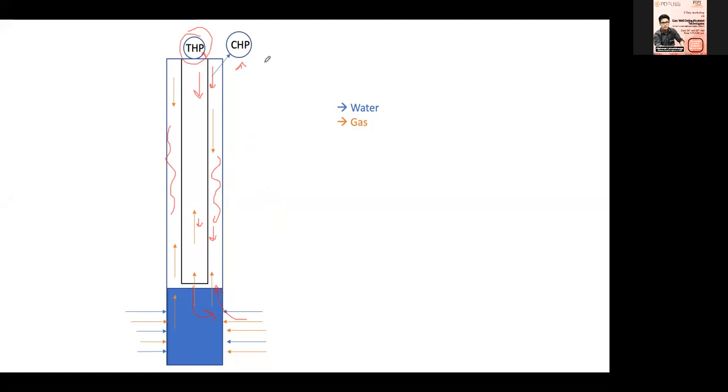Or if you want to control your gas rate, you are going to put a bean also in your wellhead. So when you are opening the flow arm valve, there is a sudden pressure drop, and because of that, some of your gas will be pushing the liquid upwards. So it will push, and then you are going to be able to unload your liquid to the surface, right?